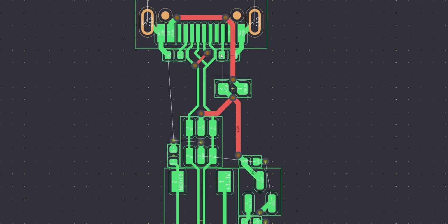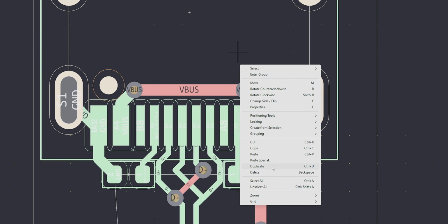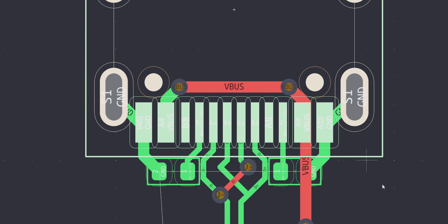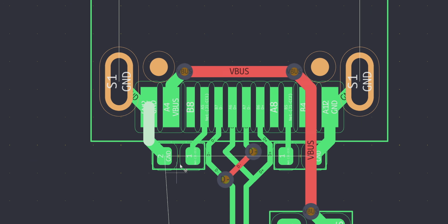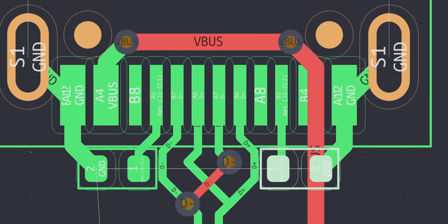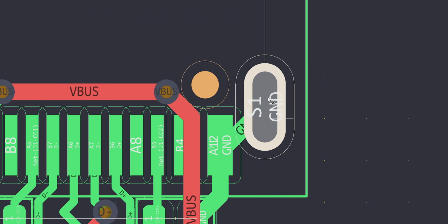But what I want to do first is break down the USB-C circuit. So if we look at this, I'm going to right click and ungroup this so I can select things a little bit easier. Basically how this works is we have our USB connector here, we have our ground from our resistors for the CC1 pin and our CC2 pin, just going into these 5.1K resistors. They're grounding out over on the shield, because this would technically be shield on the USB port, but on my footprint it's actually just ground, so that's what I was referring to.